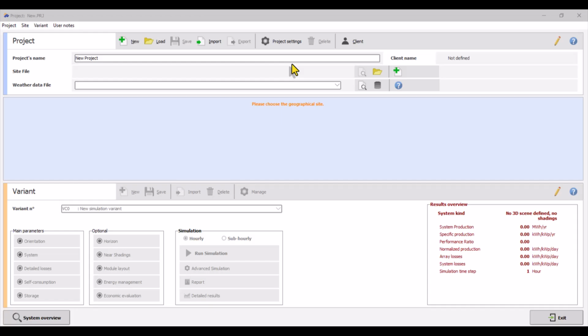To overcome this limitation, we will model the domed array using two fixed tilt orientations, one representing the east-facing modules and the other representing the west-facing modules. This approach enables PVsyst to calculate the rear side irradiance and allows bifaciality to be activated while accurately representing the geometry of a dome-shaped solar PV system.